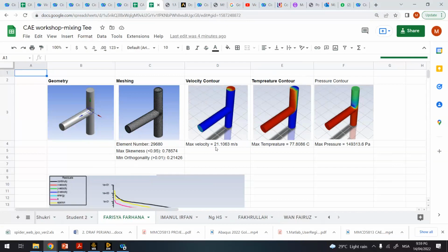If you get another value, that means your grid is not refined enough. Your grid is not good enough, so your answer changes with the mesh. So we must test our grid, increasing several grids until we are satisfied that our answer is not changing much. By practice, less than 5% is okay. Much lower is better.